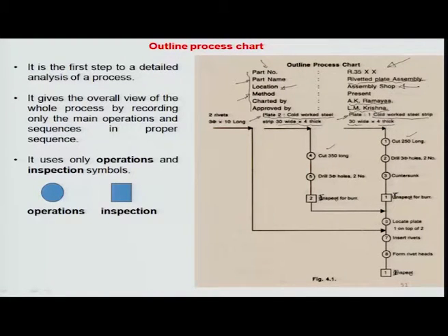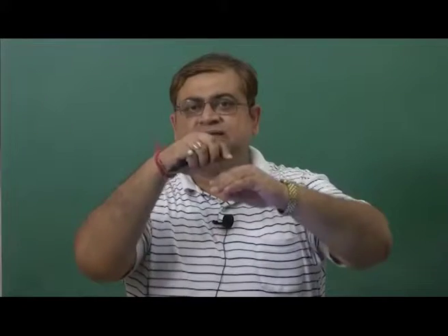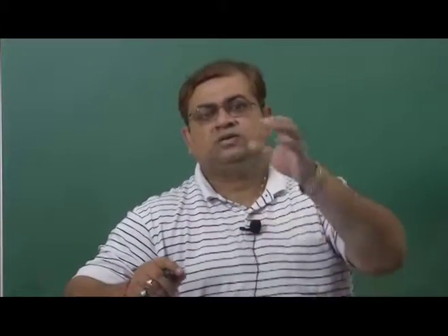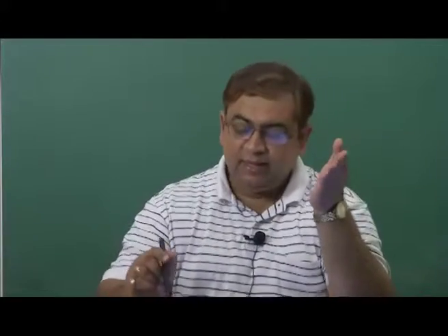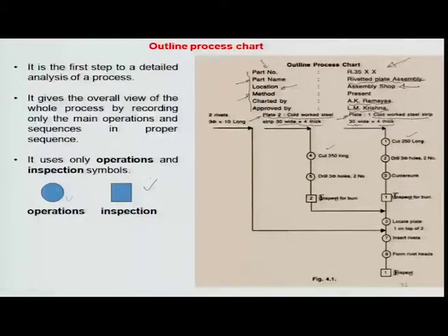So, what is the process like? You have one sheet which you are drilling separately, another which you are drilling separately, putting the two together, then bringing a rivet inside and forming, right. So, these are the different steps associated with this whole job. I have now illustrated this in terms of circles, which represent the operation, and inspection steps, which are represented by the square. You remember in the process flow these are the two different symbols being used, as shown here. So, the first operation is cutting.